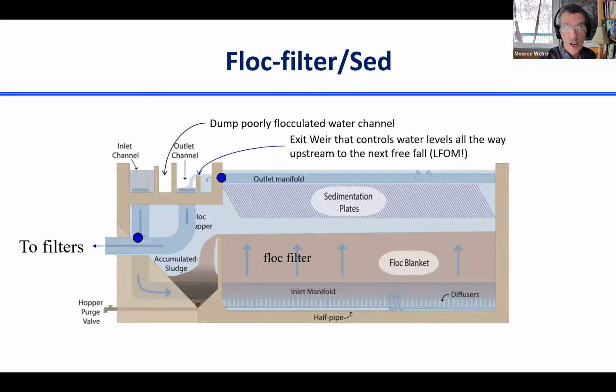It means that if you turn the water off, think about this for a second. If I turn the water off to the plant, what determines the level of water in the flocculator? There's no longer any flow. And granted, you have to give it a few minutes for everything to calm down. And once all the water stops flowing, what level will the water be at in the flocculator? Who wants to be brave? Is it the height of the water in the entrance tank?